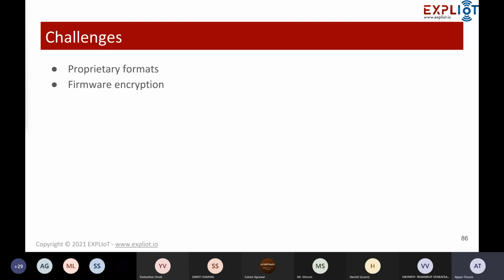And firmware encryption, again, is a challenge because you have to then understand the decryption routine and basically wait for the next patch update, or maybe go to the support, and if they have the archive or the legacy firmwares from where the firmware encryption started, you can take that particular firmware and then try to understand what public key it is using and stuff like that.